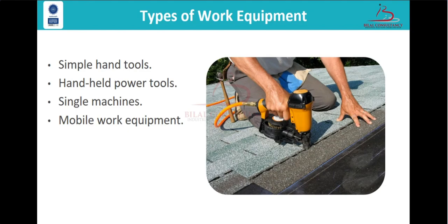Equipment must be carefully selected to ensure that it is suitable for the task and environment on the basis of the manufacturer's information. In many regions of the world, there are regulations that require manufacturers to ensure that the equipment they produce meets basic safety standards. For example, in the EU, the Machinery Directive 2006 established the basic safety standard that manufacturers are legally obliged to meet. Manufacturers are required to design and manufacture machinery so that it meets essential health and safety requirements, and create a technical file which should contain the information required to show that the product properly complies with the requirements of the directives that apply to it.